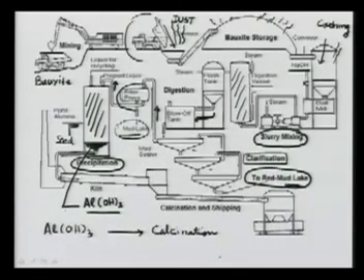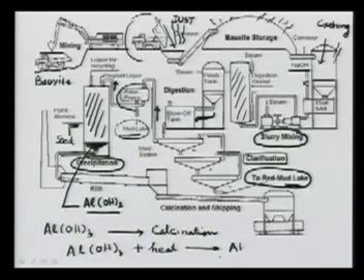We'll see in a moment how the calcination is done. But let me write the reaction as to how the calcination will occur. What we really need for calcination to be accomplished is to supply some heat. If you apply the heat, the reaction that goes through is we get Al2O3, that is what we want to get, plus we get the water out. The idea is to get the water out and get the calcined alumina.